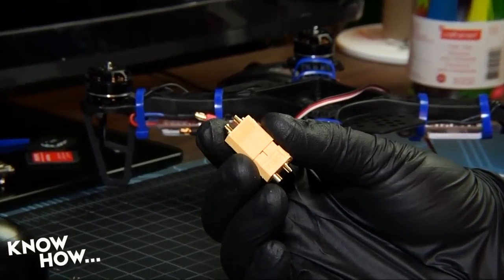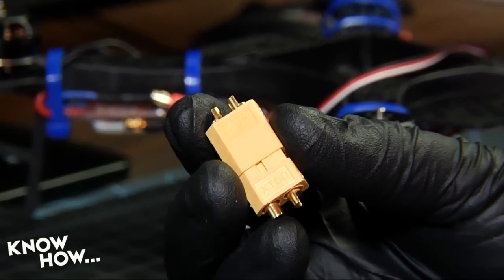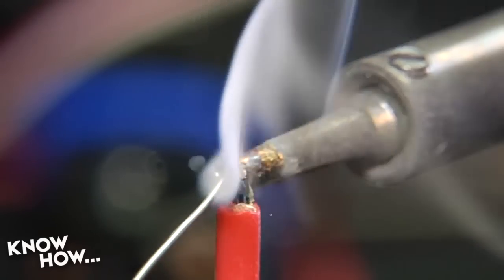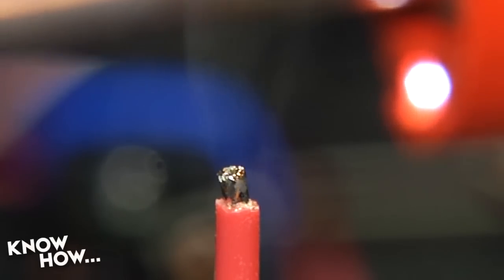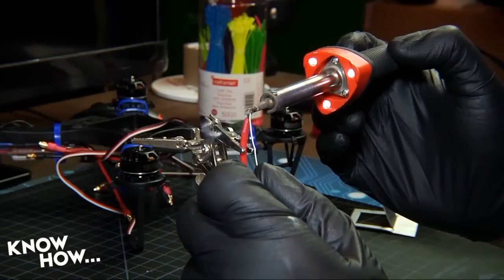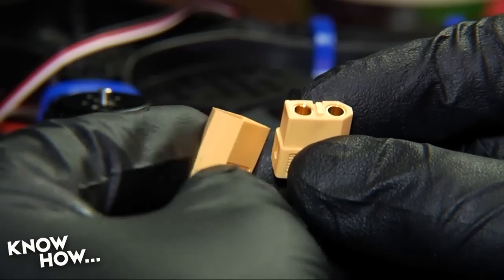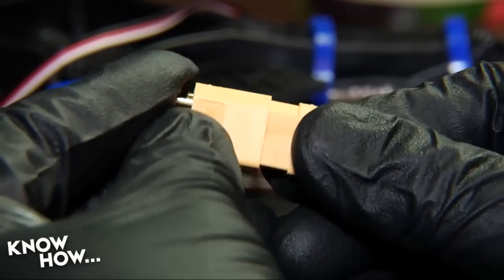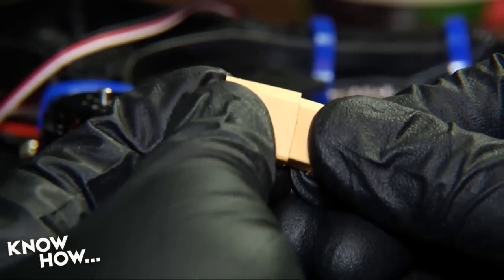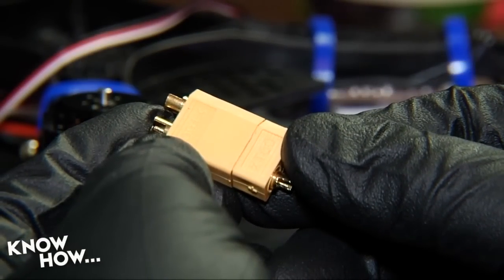We're going to be wiring an XT60 connector to the power distribution board with the pair of 5-inch wires. Strip 4mm off of one end and 10mm off the other, then tin your wires. We want to wire the female XT60 connector to our power distribution board, but we need to avoid overheating the connector, which would misalign the pins and destroy the housing. In order to solder safely, plug the female connector into its male counterpart. That will spread the heat and maintain pin position.